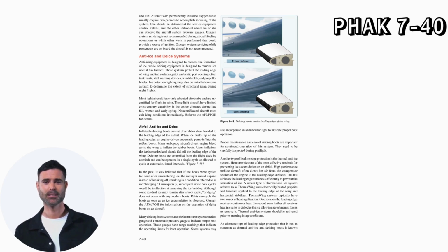Airfoil anti-ice and de-ice. Inflatable de-icing boots consist of a rubber sheet bonded to the leading edge of the airfoil. When ice builds up on the leading edge, an engine-driven pneumatic pump inflates the rubber boots. Many turboprop aircraft divert engine bleed air to the wing to inflate the rubber boots. Upon inflation, the ice is cracked and should fall off the leading edge of the wing.